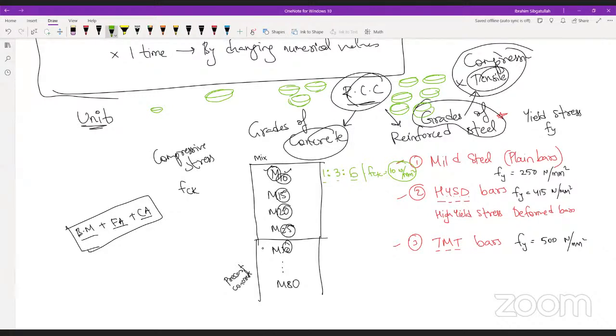Okay, there is a mold which will be open from one side, open at the top. Inside this we pour the concrete all the way to the top. Let's say this is the top. After filling, if a little concrete is showing over here, we will just scrape it out so that we have a smooth fill over here on the top.